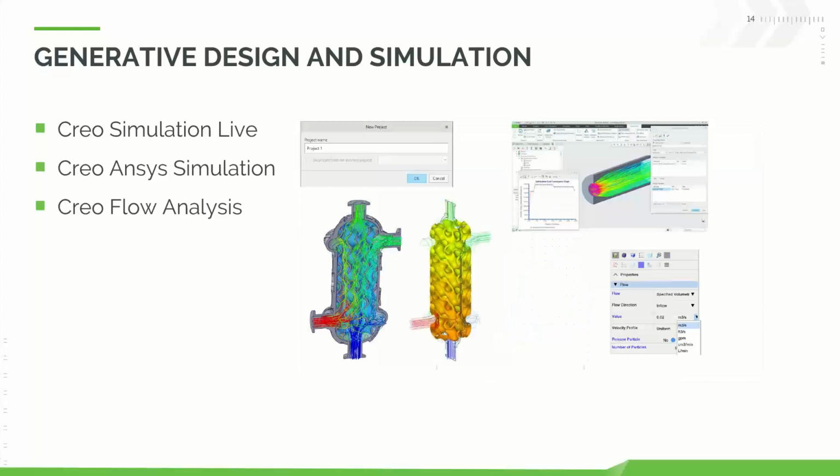Creo Flow Analysis got a number of different improvements. This has definitely been a pretty active area. You can now store multiple CFD projects within one model. You don't have to store them out separately. You can look at various ones, hop from one to the other if you'd like to. Definitely a good enhancement there. We worked on meshing with some different tessellation improvements, control over that. Support for lattice geometry, the idea of using lattices for things like heat exchangers and so forth. That can now be studied and used in Creo flow analysis.